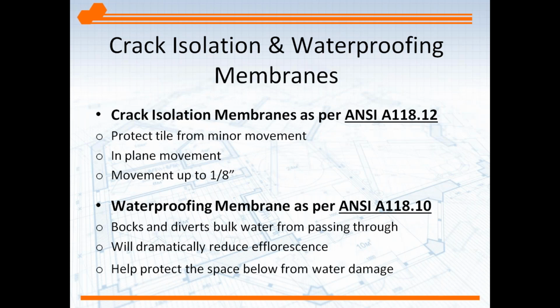On a tech data sheet, it will list whether it meets the ANSI A118.12, or maybe the setting materials manufacturer, the professional that works there, will offer that information to you. So you can see if it's apples to apples. And that goes for all those tile installation products that have an ANSI standard. It's really a big help as far as keeping the playing field level and apples to apples as far as performance of the products.